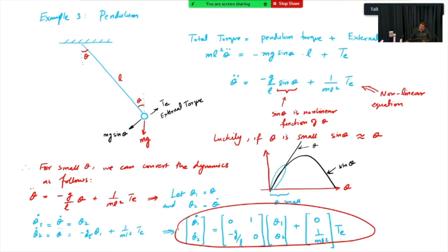And the good thing is you always linearize systems around 0, and the reason is because when you use a feedback control system, you always want your input signal to be 0 because you're comparing against a reference signal. So the system input is always reference minus the current state, and that should be as close as possible to 0.